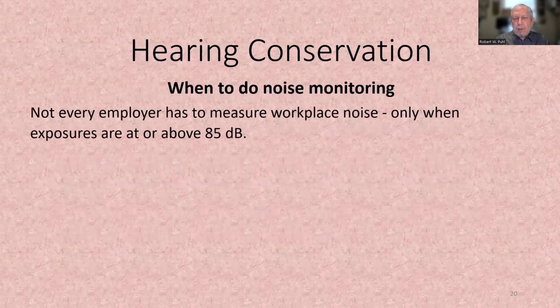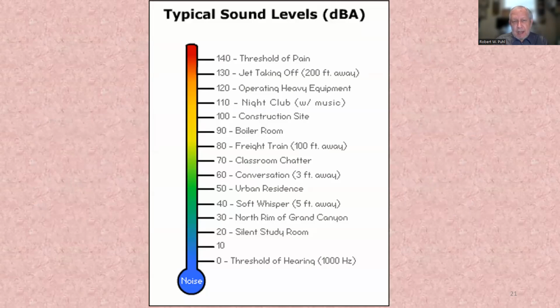So, when to do noise monitoring. Not every employer has to measure workplace noise. Not everybody has to do it, only when exposures are above 85 decibels. Well, if you don't measure it, how are you going to know, right? But this is kind of, I don't want to use a thermometer for it, but a noise thermometer.